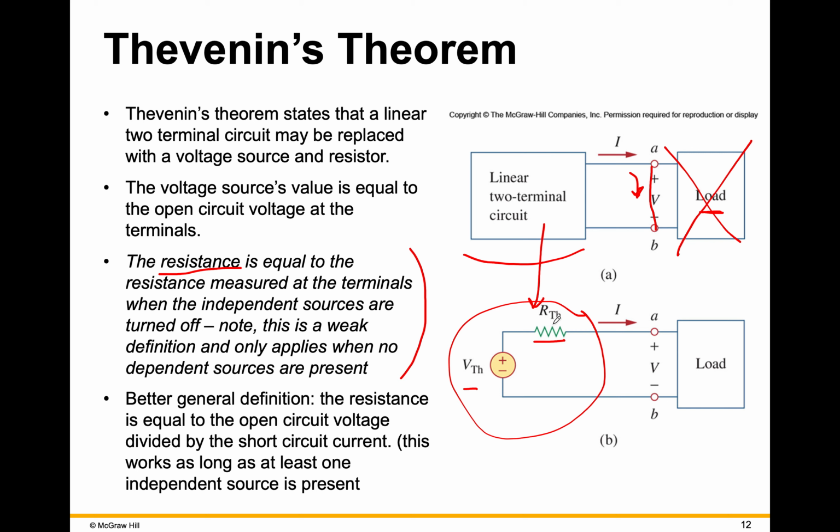The other thing is, it is extremely easy to make an error when doing multiple source transformations and resistor combinations. First of all, you have to be very good at recognizing what's in series and what's in parallel. You have to have some intuition about which source transformations to do and the order in which you do them. If a circuit gets complicated at all, the number of steps becomes increasingly large. You may end up having to do Y to delta transforms on your resistors, and that gets very complicated. So if you're not really good at seeing the geometry of the circuits, my opinion is that is more trouble than it's worth, and you're better off just using node voltage or mesh current.